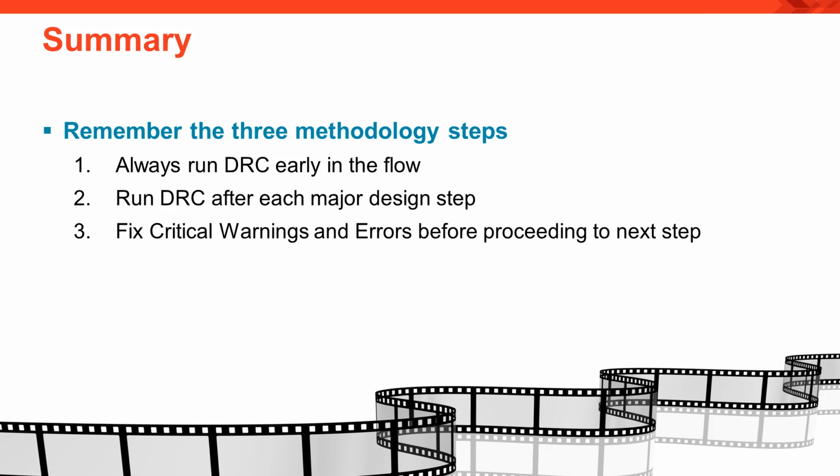Always run DRC early in the flow, run DRC after each major step, and fix any critical warnings or errors before proceeding to the next step. If you follow these 3 simple steps, you will ensure maximum efficiency for working with DRCs.